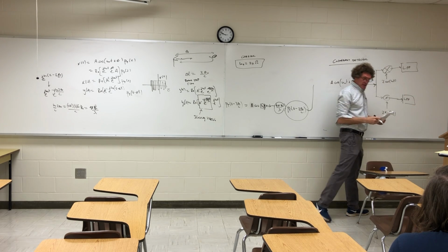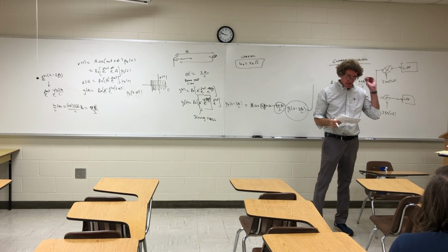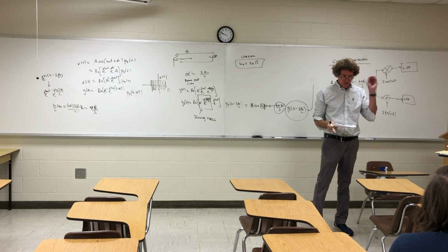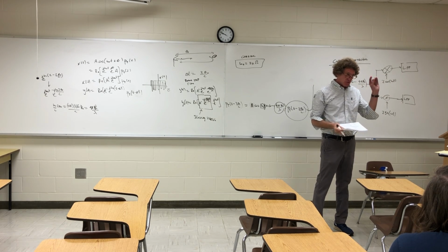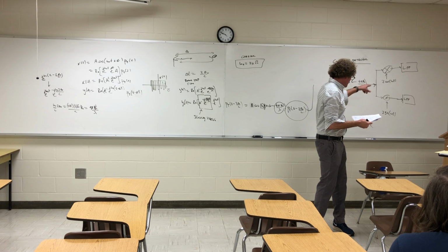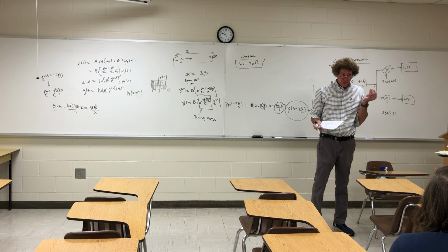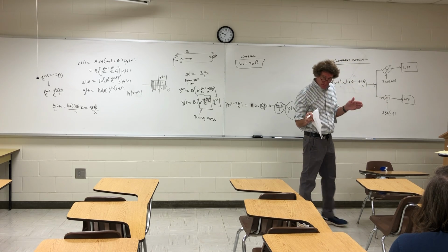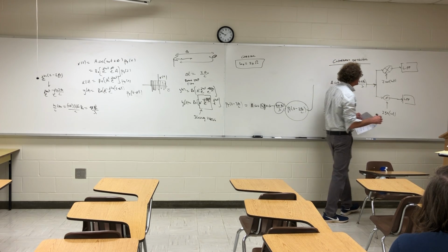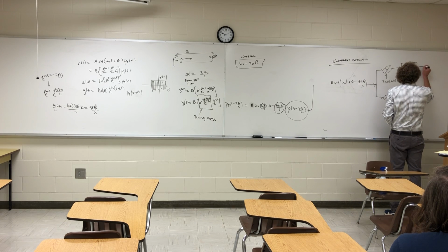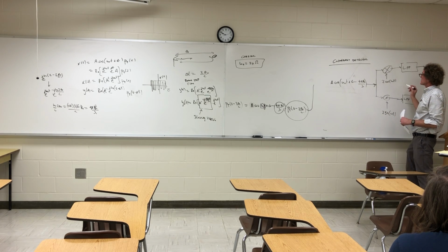Last time I said, instead of doing a standard low-pass filter, you could actually sample it at the frequency of omega naught. If f naught was the frequency, you'd sample it at 1 over f naught, and you could actually down sample things so that you would get baseband through a low-pass filter. Y'all remember this? This is one way to do it. Now, the output here, I was messing with this last night.